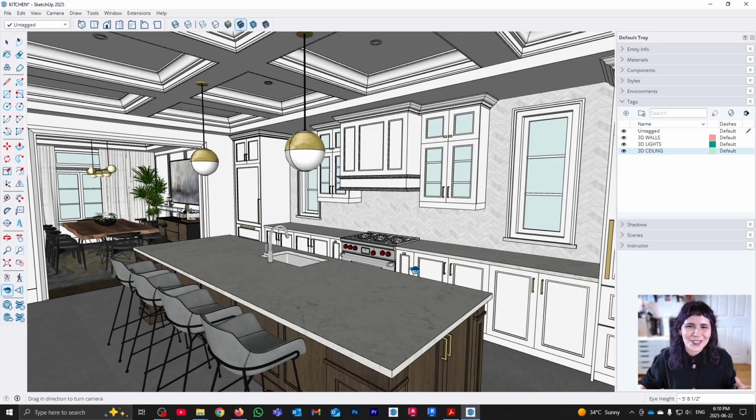And this is why I was being careful setting up my camera, because I wanted you to see how messed up it is. So if you look here at this edge, see how my cabinet goes kind of like, ooh, it goes in. And then you can also see it here with the trim of this opening. You can see how it goes like this. So right now we are working in a perspective. That means that all angles of my model are being distorted. You have to understand that the rule, thumb close, big, thumb far, small, doesn't work just in a horizontal. It also works in a vertical. That's why the top of a building looks so tiny compared with the base of the building. So if you are in just a regular perspective, all directions are getting distorted by the perspective.